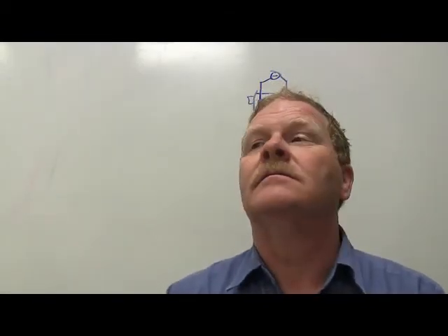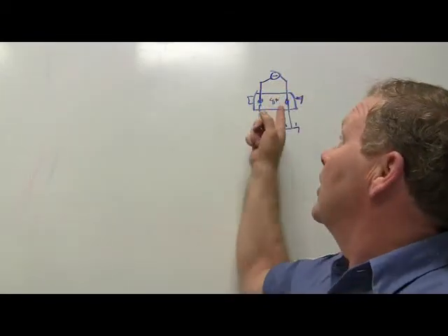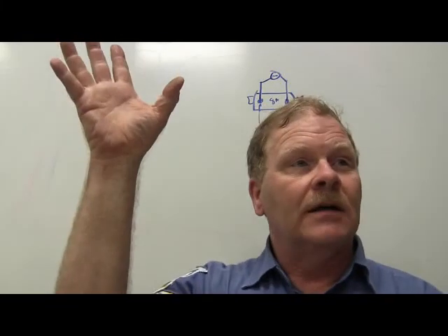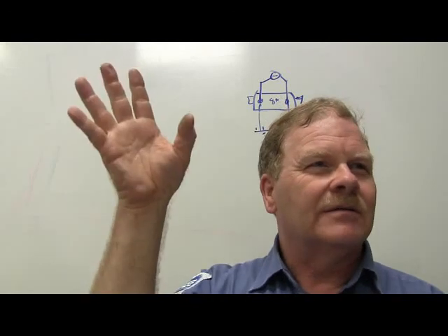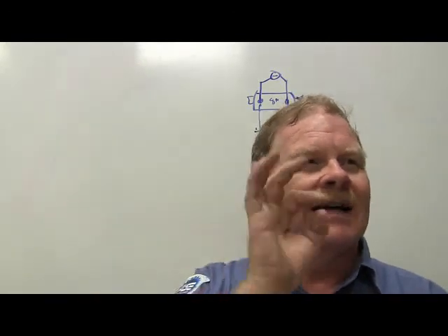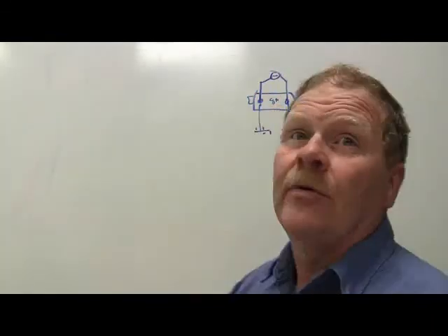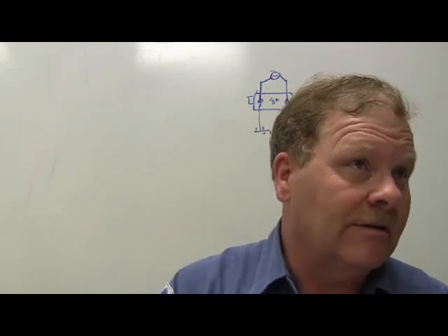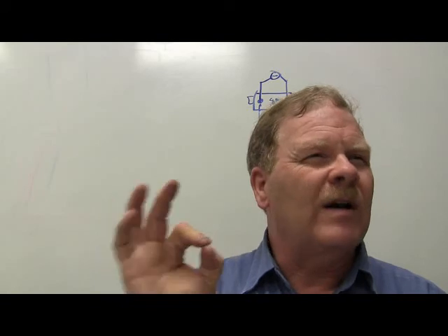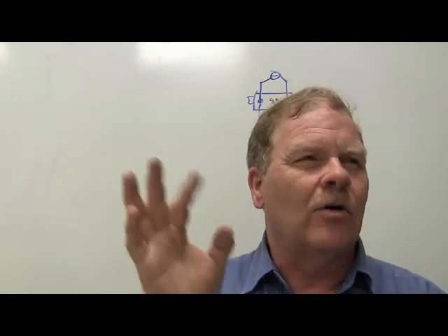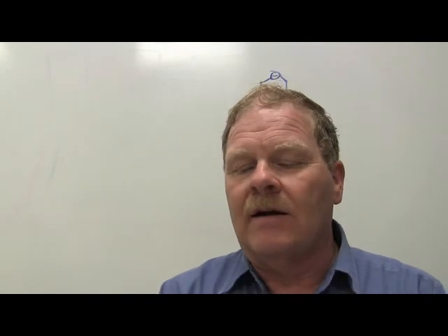Everybody clear on that? So that light is flickering. It's actually that circuit breaker. When that shorts there, it's going to open, it's going to cool off, it's going to close. It's going to be about every second or so. Ding, ding, ding, ding. Now do not, under any circumstances, take something like a 30 amp fuse and put it there, because you will burn up wires if you do that. I've seen that happen. You want a really weak circuit breaker that will reset itself, robust but not pulling a lot of amps. That's really, really important.